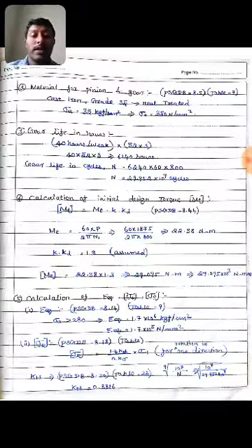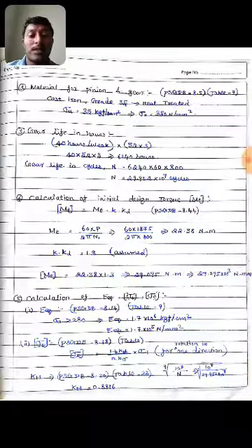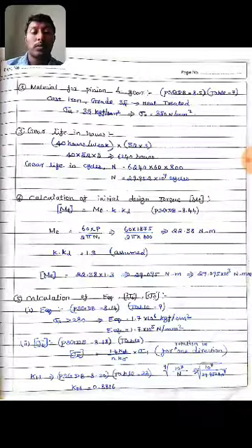First one, EEQ from the PSG data book page number 8.14 from the table 9. Sigma U is greater than 280 means EEQ value 1.7 into 10 to the power of 6 kgf by centimeter square. We change into Newton per mm square means EEQ is equal to 1.7 into 10 to the power of 5 Newton per mm square.